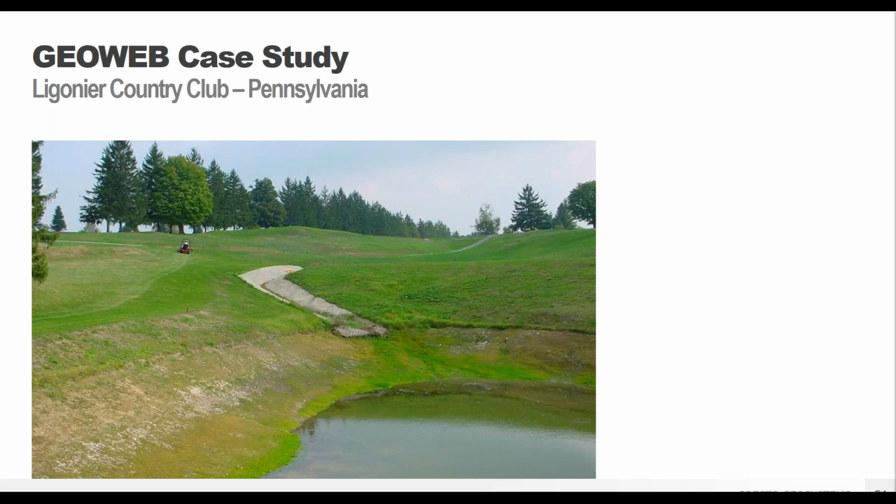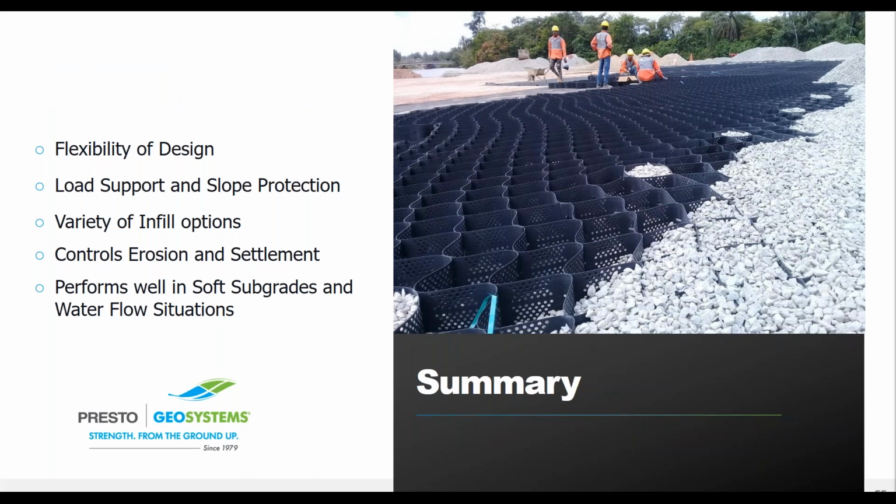And again, you have the potential to reduce the cross-section depth of the concrete because it's confined within the GeoWeb panels. You can go as low as that 3-inch panel that you typically couldn't do with a reinforced concrete if you were to have rebar in there, because you need a certain amount of depth on either side of the rebar that you don't need when you're using the GeoWeb system. So it's another way to help reduce the amount of concrete that would be necessary.